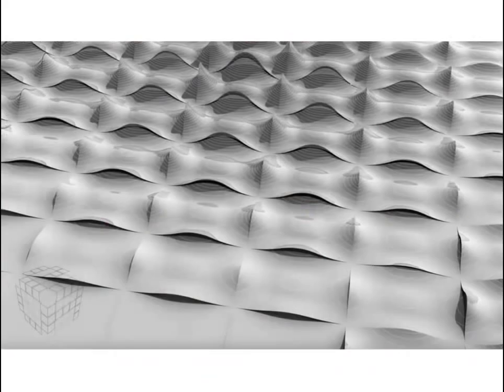And you could get different operations like this surface. So again, this thing's been tiled, but the variance here is that these points... There's probably a curve here with a point in the center, a curve here with a point, and the z coordinate of that point is changing parametrically. And when that curve is redrawn, you get that bulge, or almost like a fish gill opening up. We'll talk about these later in a future class. But basically, you take those curves and that makes a surface.